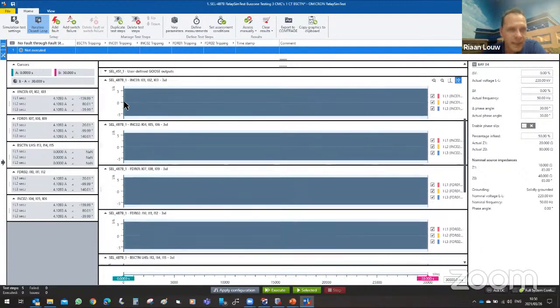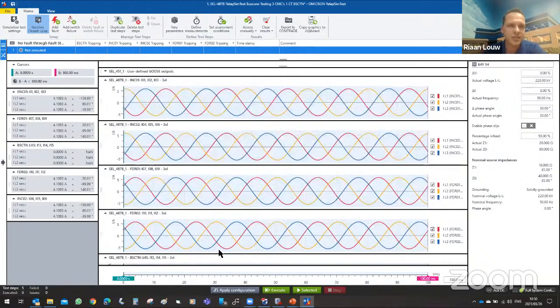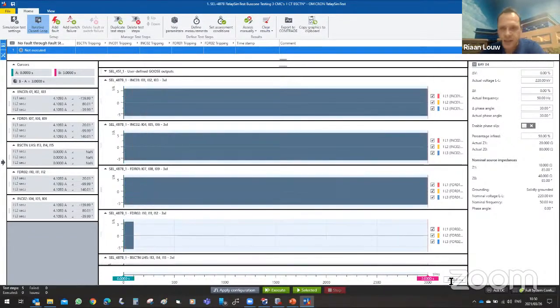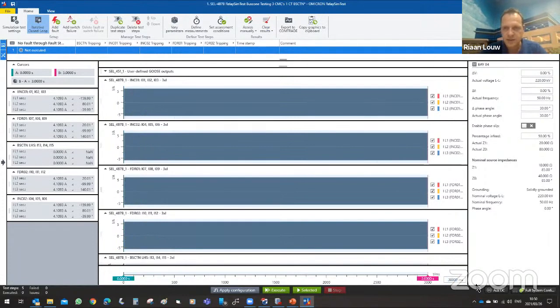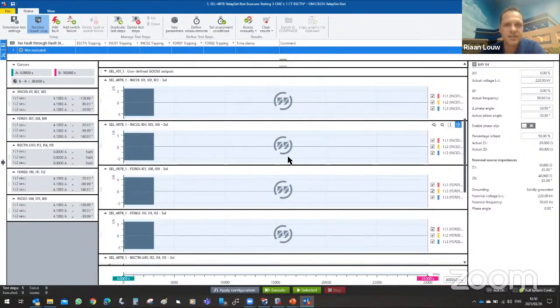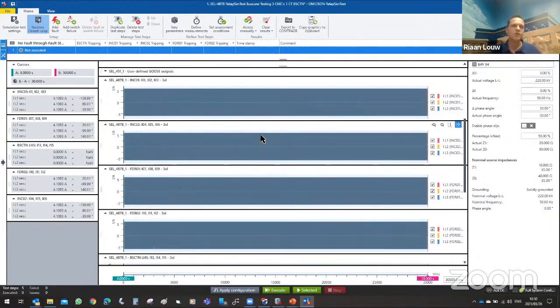So you'll see this completely gray bar here. Actually, that is my transient currents. If I quickly make this 100 milliseconds, you'll actually start seeing that these are the currents being displayed. The only reason why is, if I simulate this test for 30 seconds, it condenses all of those waveforms into 30 seconds, and it's simply compressing it together so it now looks like just one solid bar. But in reality, these are your currents in the background that are being simulated.